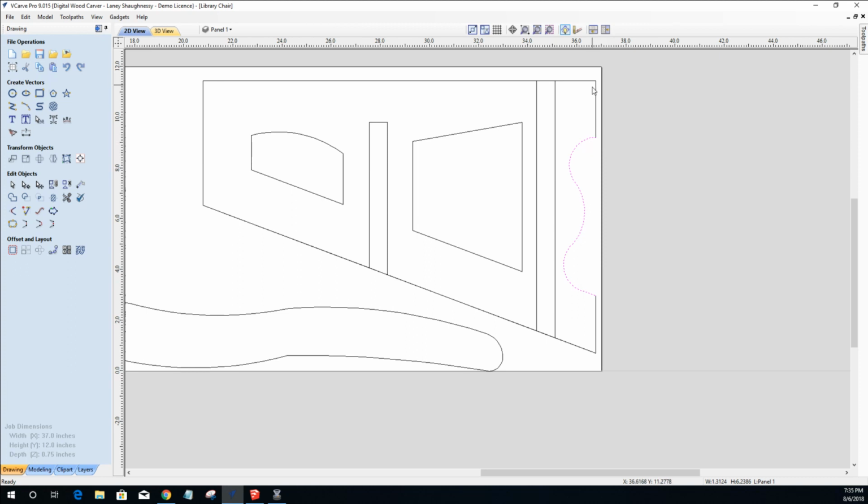I don't recommend having it flat and square across the bottom. I think the chair should sit on two points, should land on two points versus across the surface. If you have a straight bottom coming across, well, if you're on an uneven floor of some sort, then you're going to get rocking and things.